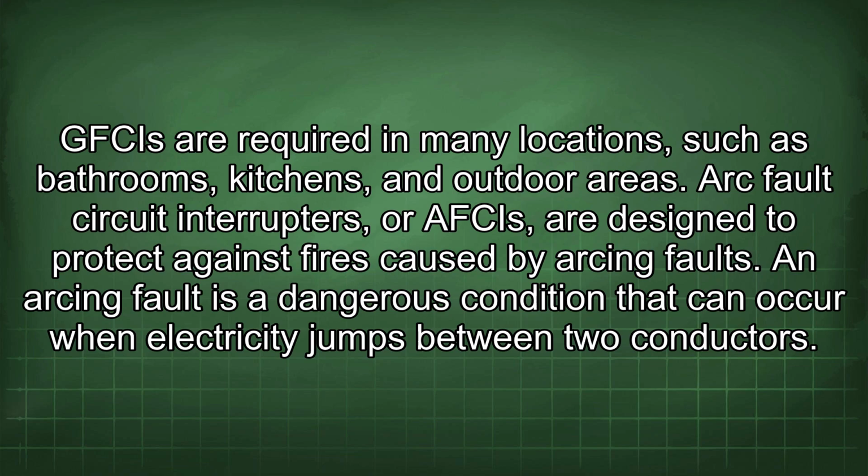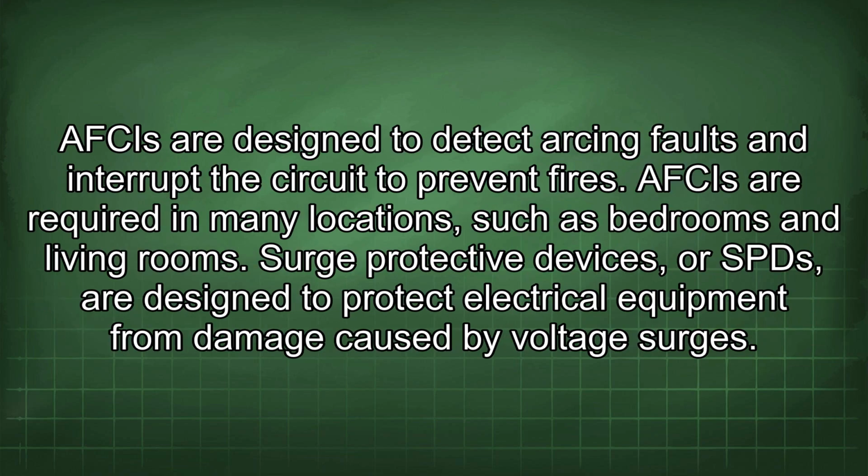Arc fault circuit interrupters, or AFCIs, are designed to protect against fires caused by arcing faults. An arcing fault is a dangerous condition that can occur when electricity jumps between two conductors. AFCIs are designed to detect arcing faults and interrupt the circuit to prevent fires. AFCIs are required in many locations, such as bedrooms and living rooms.